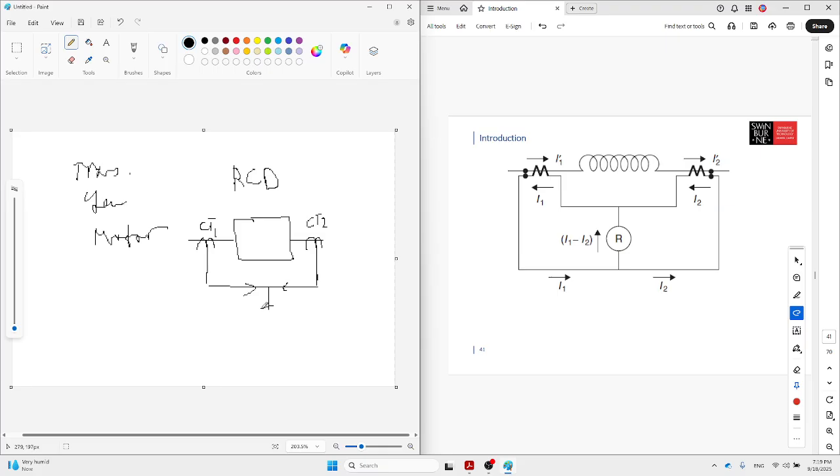So the operation coil is here. If the current of CT1 and CT2 are exactly the same, maybe this is the better way I can explain. Exactly the same, they should neutralize each other, whichever way. I can explain both. This one is not operating, but in the case of a fault inside the transformer, inside the motor, and inside the generator,